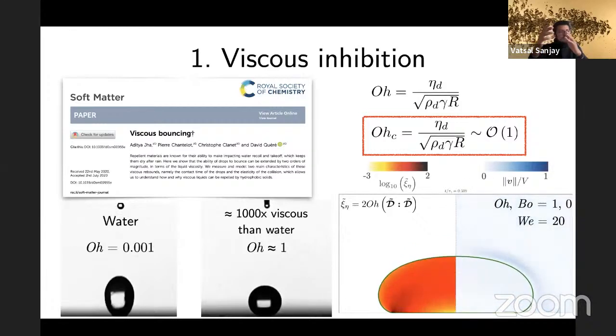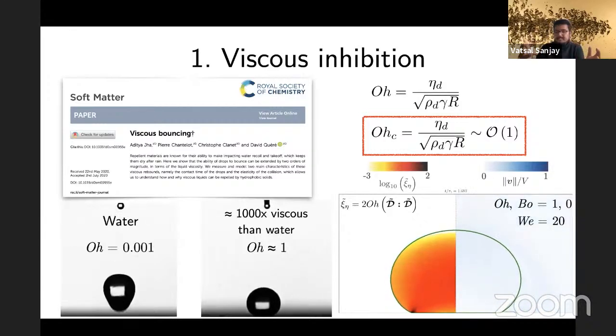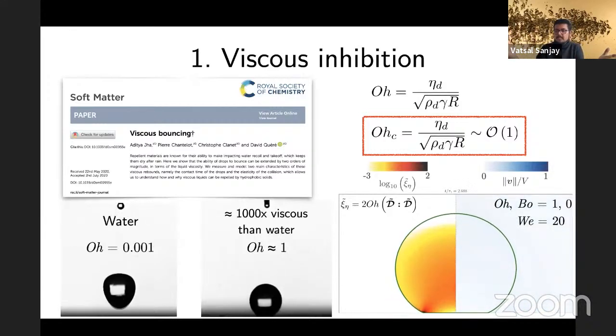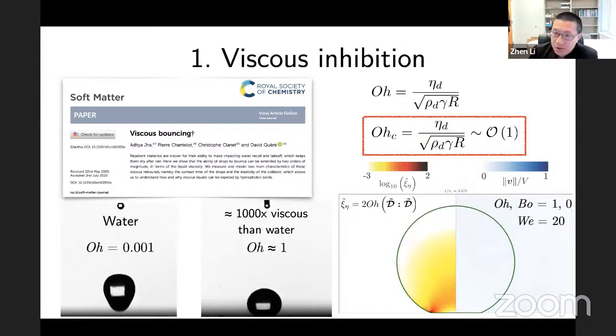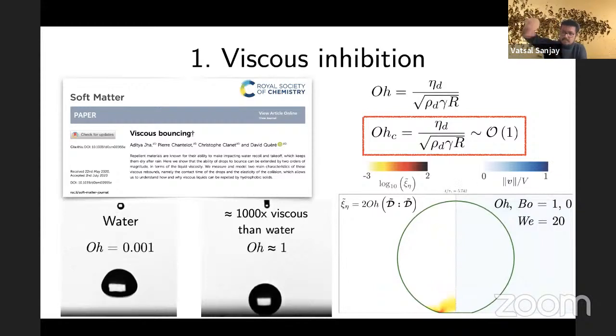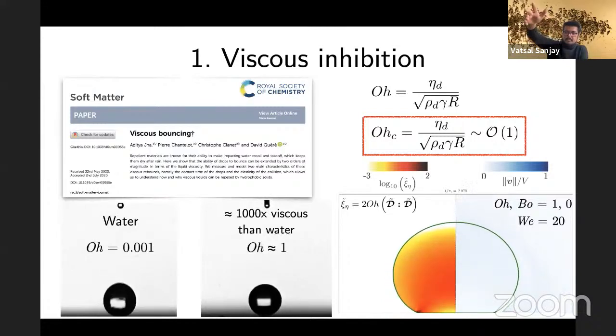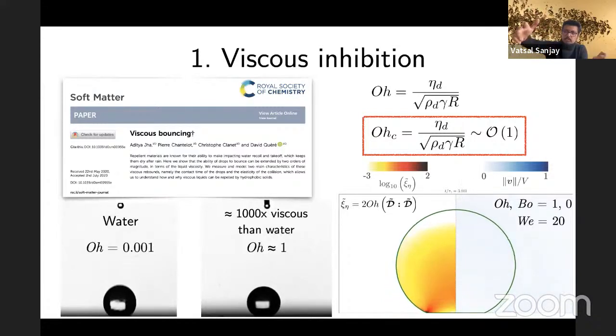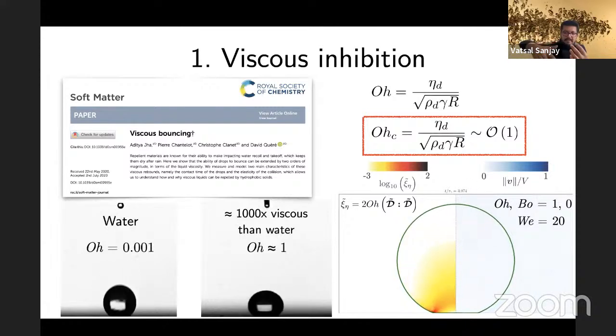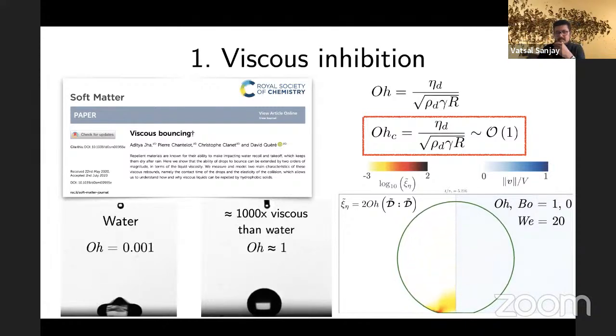By that time, the drop has already lost most of its kinetic energy because of the bulk viscous dissipation. I think for this case the Bond number is 0, so the drop is trying to go to a spherical shape, because that's the equilibrium shape. The flow velocities are quite small, and probably it's just numerical errors at that time.